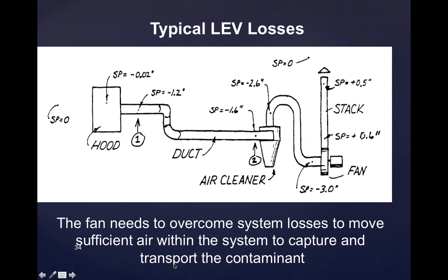The static pressure tells us the potential energy. That tells us how much static pressure we have there, tells us how the hood performs, right? We can look up in references what static pressure we need at that point in order for that hood to generate a certain capture velocity. Remember those formulas that we have on, I think it was chart 11?